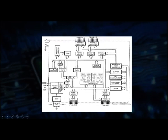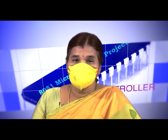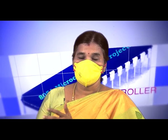All ports are bidirectional. Port 0 is not only used for input and output lines, it also multiplexes the address and data lines. The lower address lines, A0 to A7, out of 16 address lines, are multiplexed with the first 8 data lines, so AD0 to AD7 are available along with input output lines on port 0.